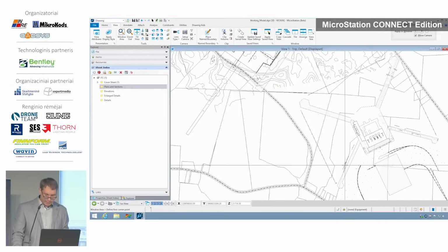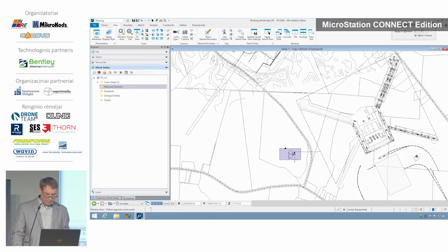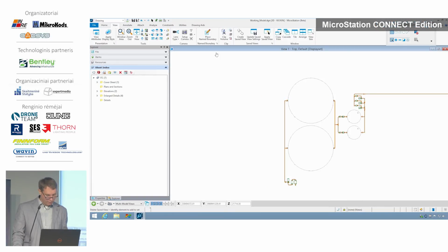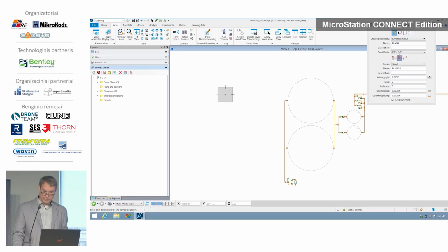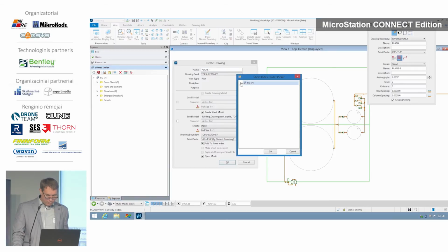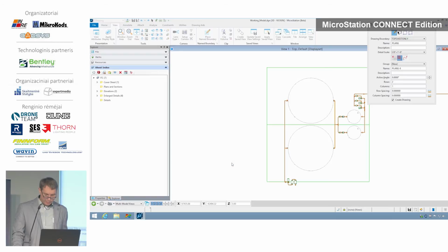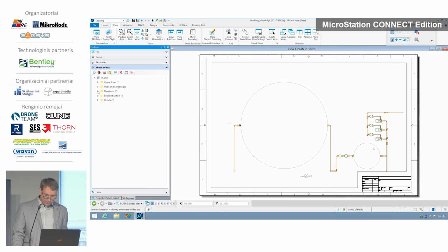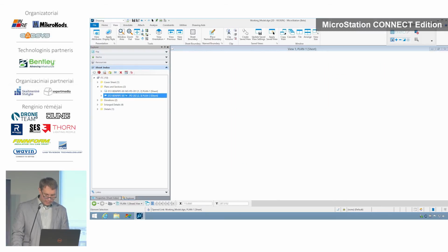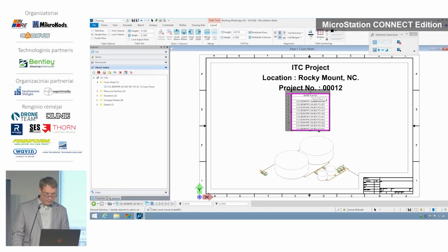The documentation center allows you to produce output faster and use the information which is stored in BIM models. Here, Connect Edition can control the symbology of drawings based on the information, these properties inside or attached to the objects. So when your model changes, you don't need to manually check or correct model symbology because it's already done automatically.